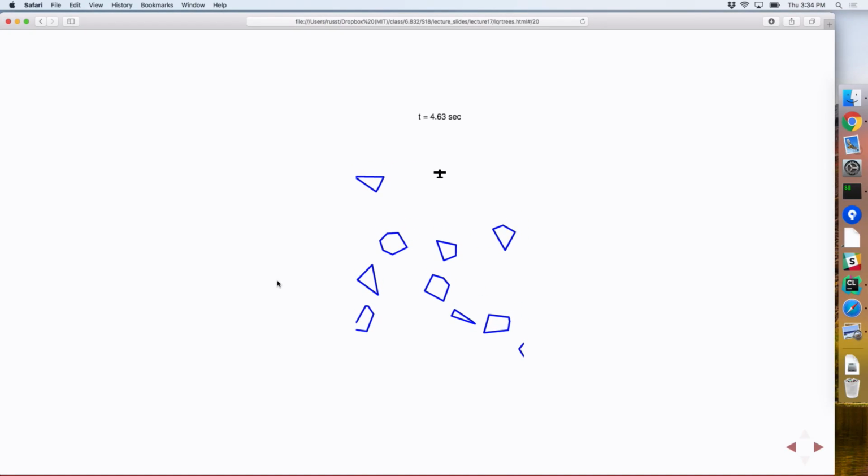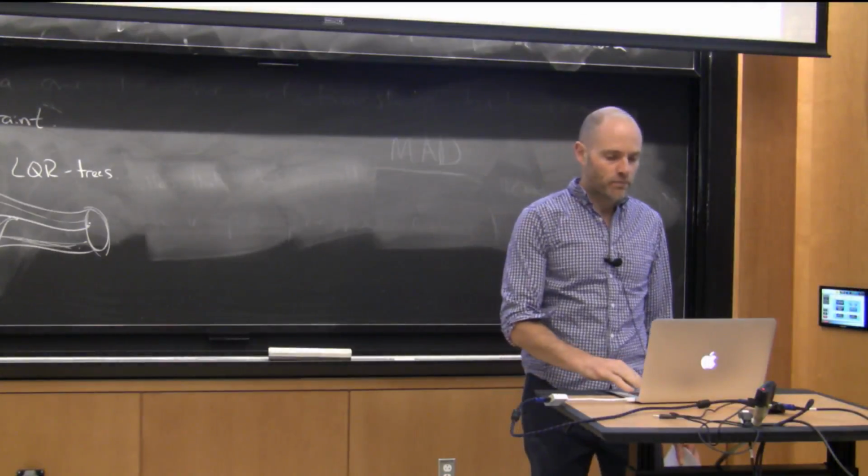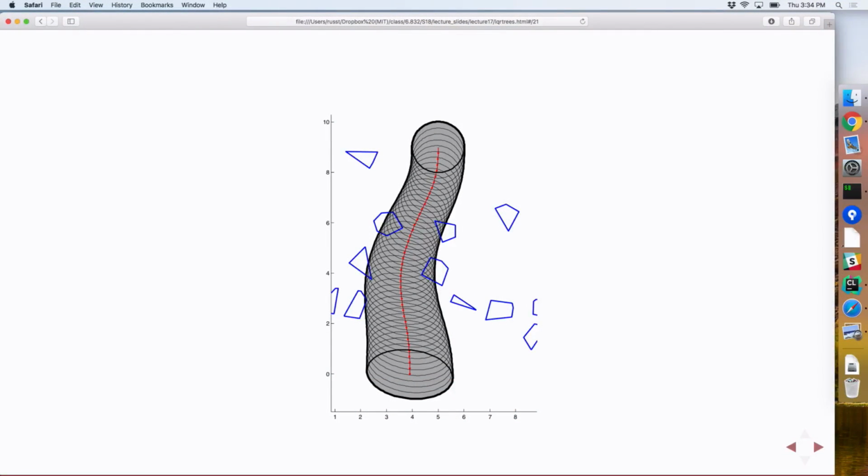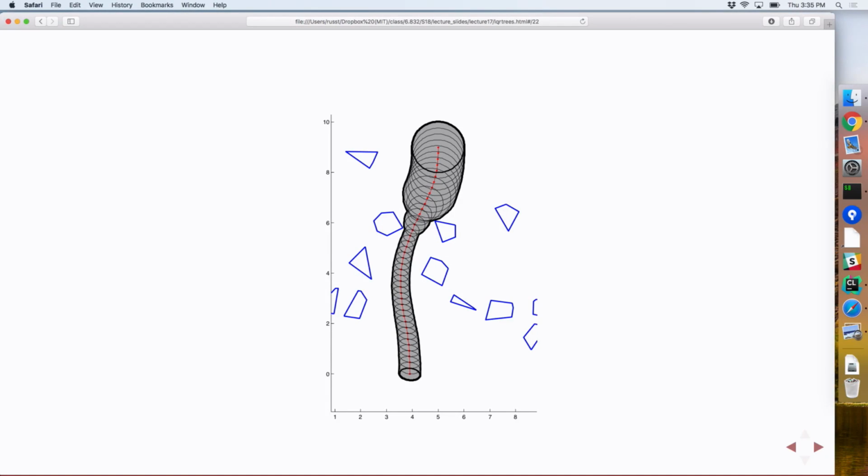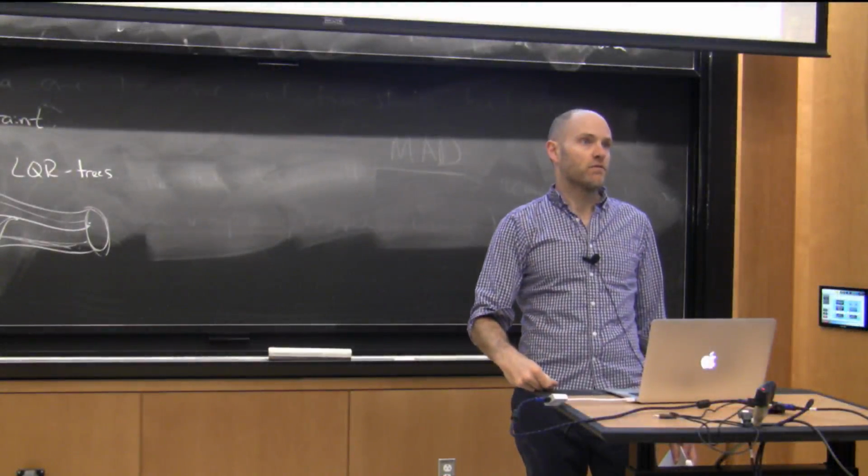So just to say, once the sums of squares stuff was able to accommodate inequality constraints nicely, then you can start doing things like this. Let's say for the unconstrained airplane, executing a particular trim or slight maneuver, the region of attraction, or the funnel, looked like that. It's a finite time region. Then at runtime, when you have new constraints, you can chop down the funnel. The picture looks like this, and with very little online computation, you can apply that funnel library to new initial conditions, right?